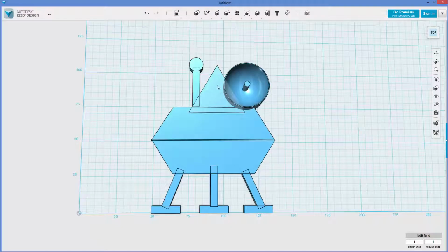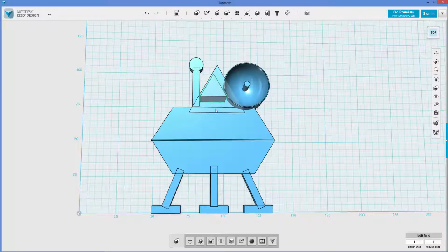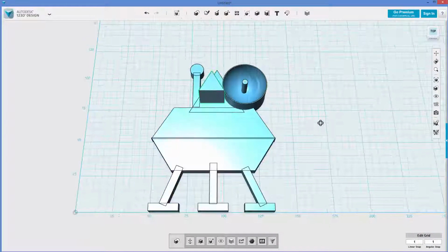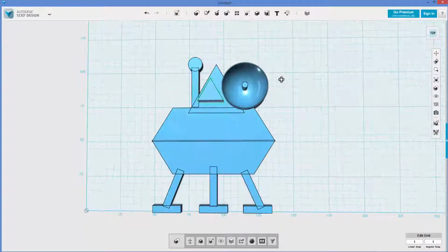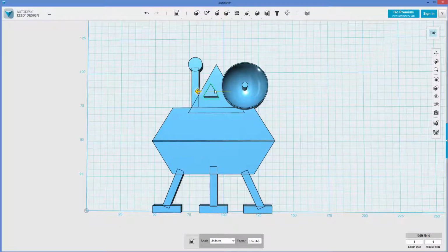All right. And then finally a window I'm going to add. So I'm going to add a wedge, put it there. Now it needs to be down inside the shape, so I'm going to hit the D key. And now I'm going to scale this down a bit to get a window. And I'm going to Control T to move it, since we've got this selected.